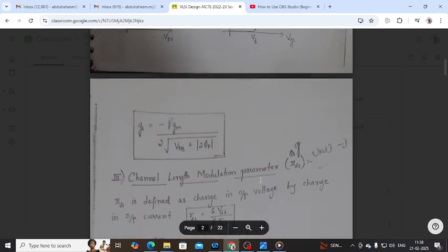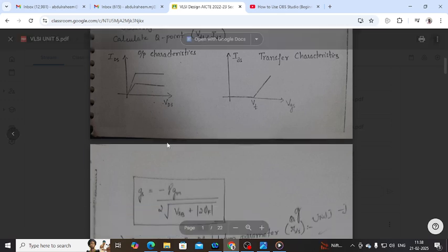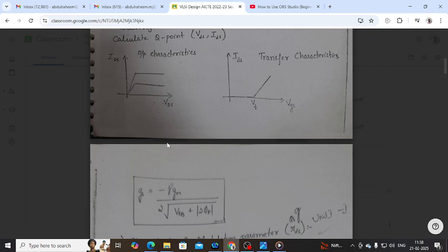Now let us try to understand a little more about the common source amplifier. You need to look at some parameters already studied from your VLSI design perspective. There are three important parameters associated with the transistor: the transconductance gm, the drain resistance rds, and the amplification factor.